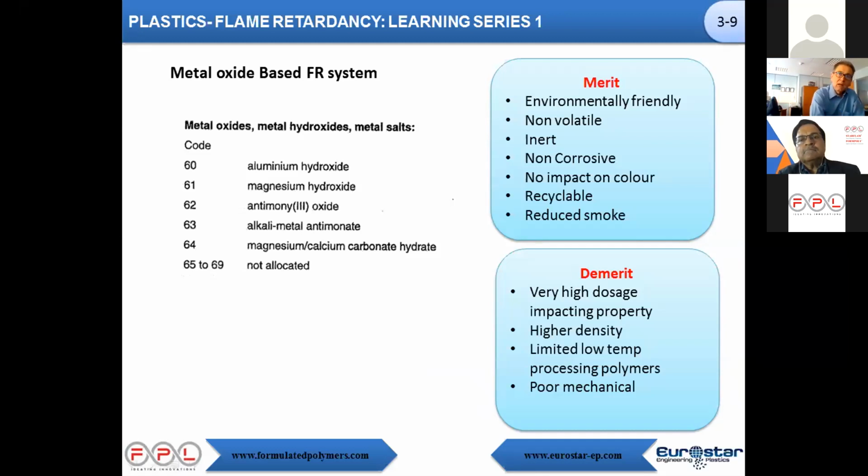Of course, aluminium trihydrate is not stable enough for polyamide. For polyamide, we're using mainly magnesium hydroxide. It's the same thing. You have a molecule of magnesium linked with water, and when we overheat this material, you are releasing some linked water.